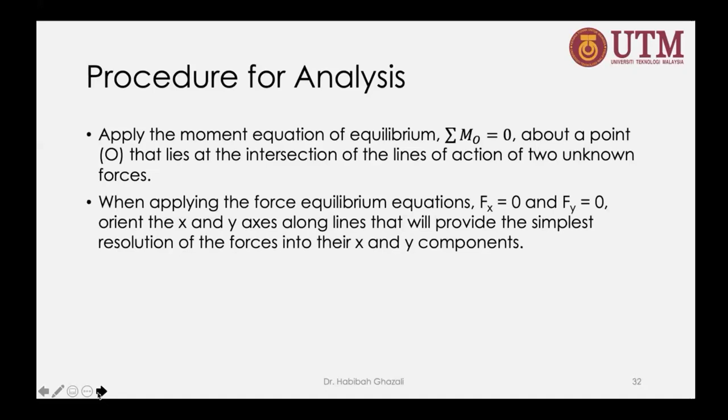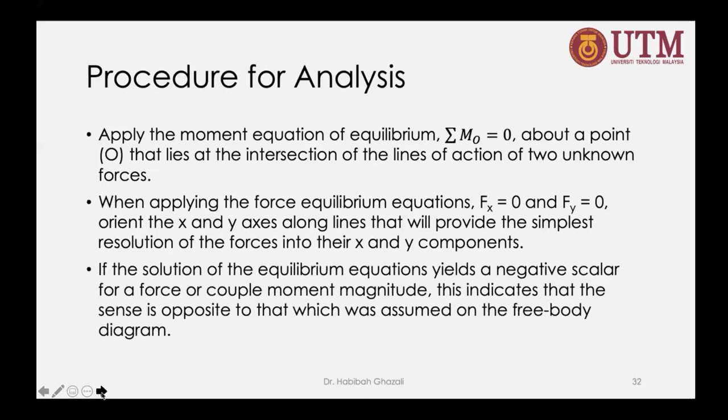So when applying the force equilibrium equations, Fx and Fy, orient the x and y along the lines that will provide the simplest resolution of the force into the x and y components. So if you have a structure like this, okay, and there is a force going this way and a force going that way, and this is a pin support.